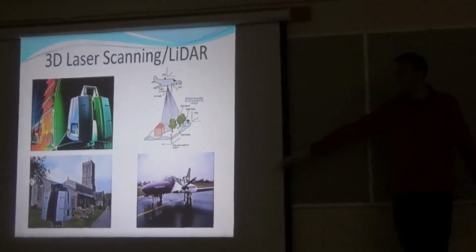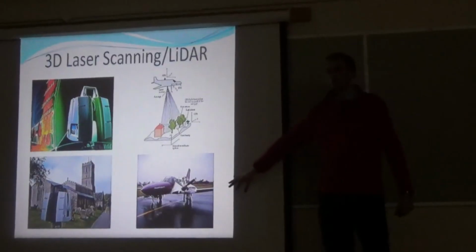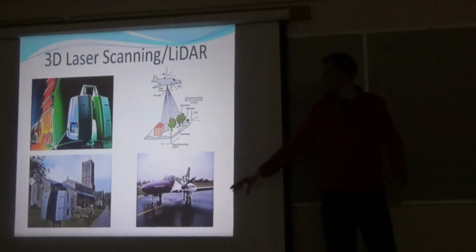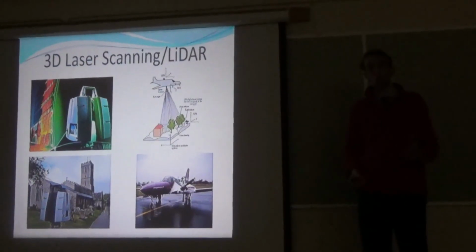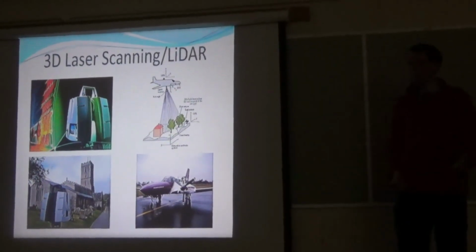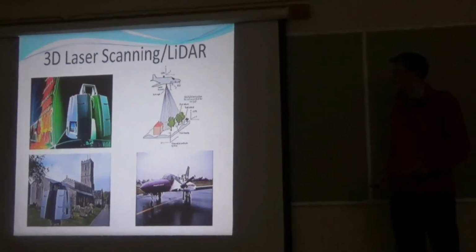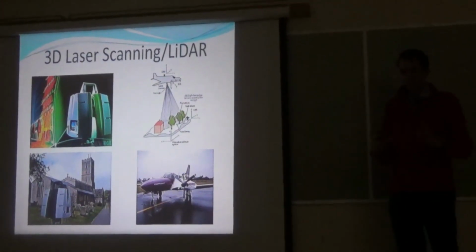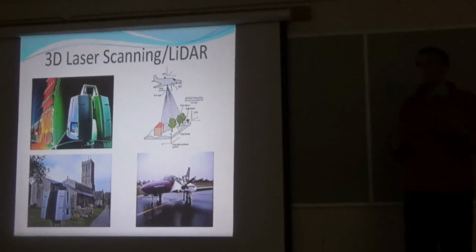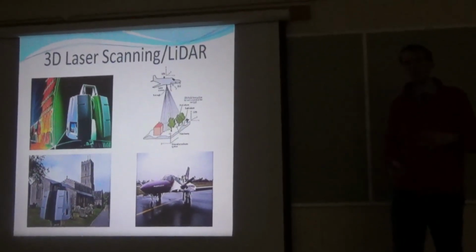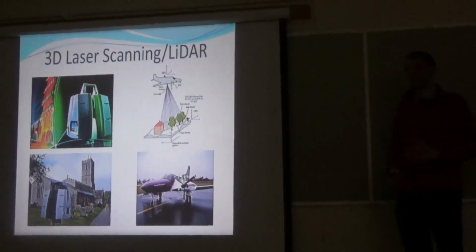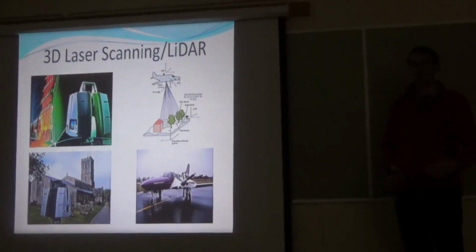It's done by the Environment Agency. You can access the data free online. Anyone can access this data. It's mainly done for flood prevention works, so if you're in an area of flooding, you get better data. And they'll usually take data in metre resolution. So you get metre resolution on the X and Y axes, and sub-centimetre resolution on the Z axis, which you're getting using lasers.